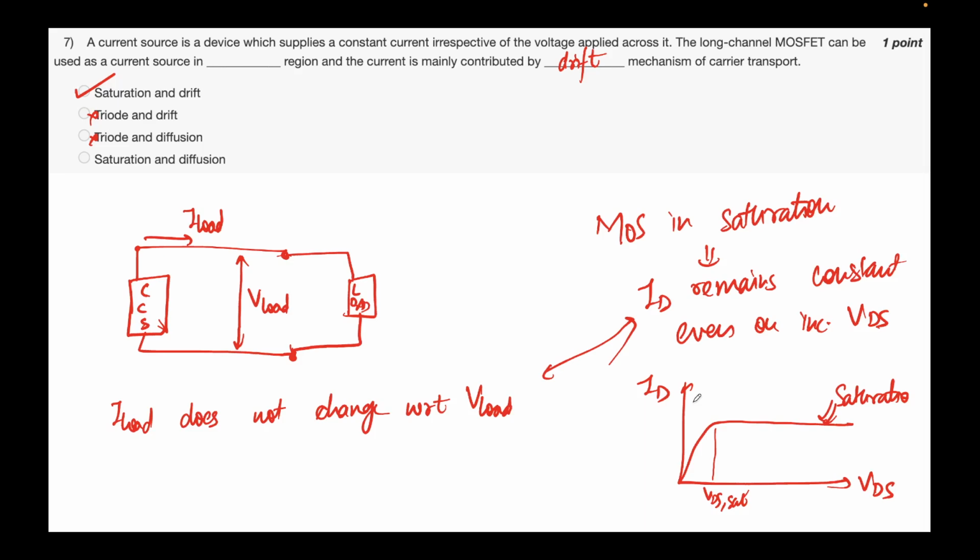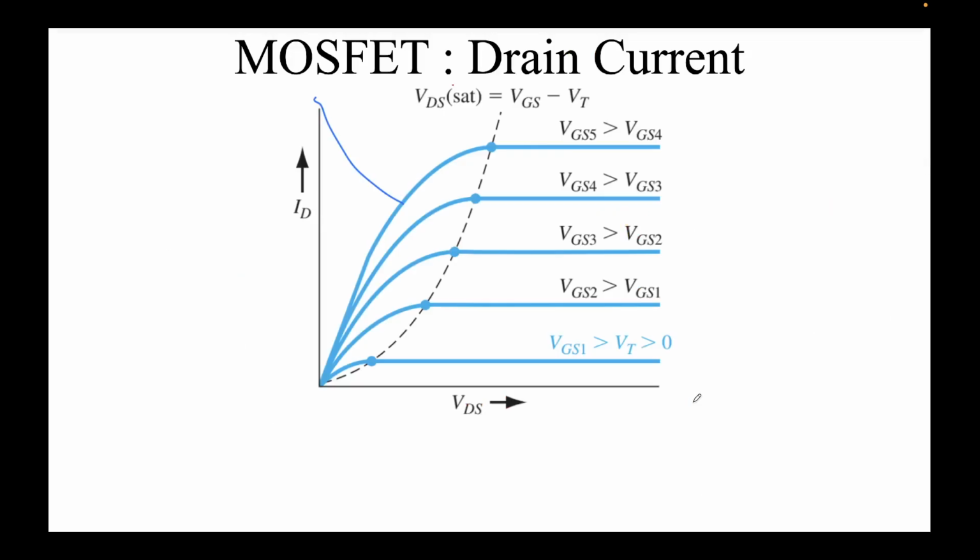We had already talked about this: since we have entered the depletion region and a strong electric field exists between the pinched off point and the drain, the electrons can simply be swept away. Okay, fine. As I said, the whole picture that we had talked about, the three regimes, if you recall. First I had told you was the cutoff, which is not drawn here, lies somewhere over here, the red line. But the current is essentially 0 because Vg is less than Vt. No inversion layer is formed, no current will flow, or rather, a very small amount of current will flow.